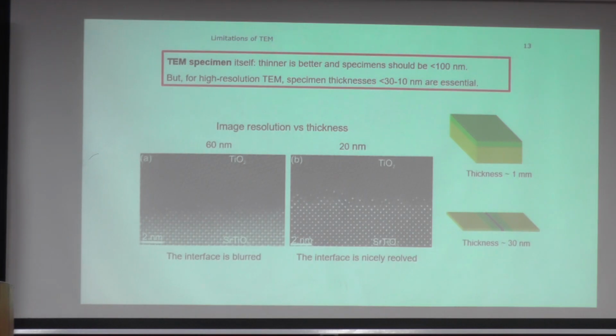Also, one limitation is the TEM specimen preparation itself, because for TEM work we need specimens which are very thin, less than 100 nanometers. And I speak about this projection: if your beam goes through your specimen, this specimen should be less than 100 nanometers.